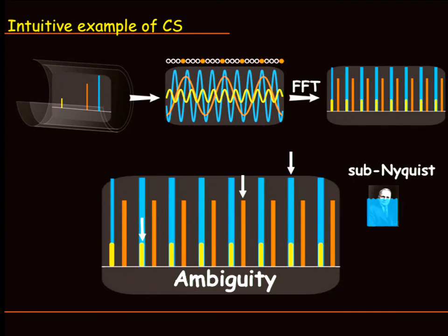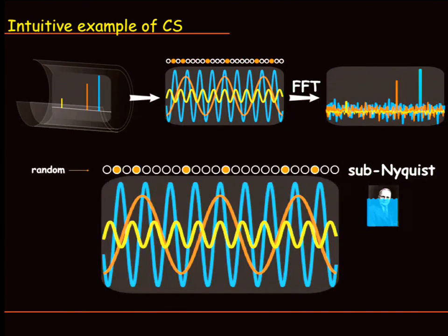I did mention what happens if you do non-uniform sampling. Let's try non-uniform sampling. If I non-uniformly sample measurements of that sequence and take a Fourier transform, I will still get this aliasing, or this wrapping of frequency on top of each other. But now it's not going to be coherent.